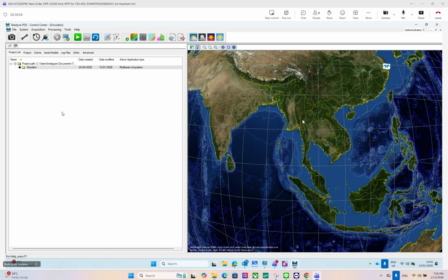You also have a laser scanner on there. So you should also measure from the laser scanner to the IMU. So you'd measure from the laser scanner's optical center, from wherever it's taking its measurements. You'd have to look at the laser scanner's manual to see from where you would need to take that measurement. Let me just emphasize that